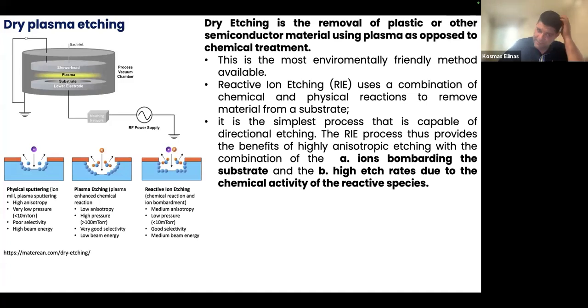In this type of etching, we have ion bombardment from the ions existing inside the plasma, which mechanically etch the material inside the feature we want to etch. And of course, reactive species do chemical etching on the surface. The combination of this mechanical and chemical etching provides a quite high etching rate, resulting in different shapes, different aspect ratio profiles.